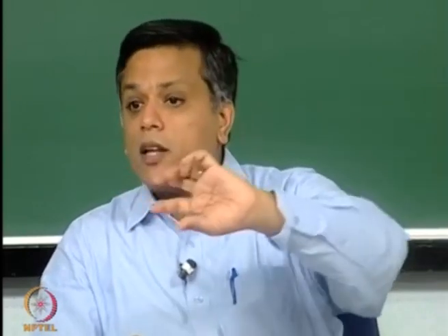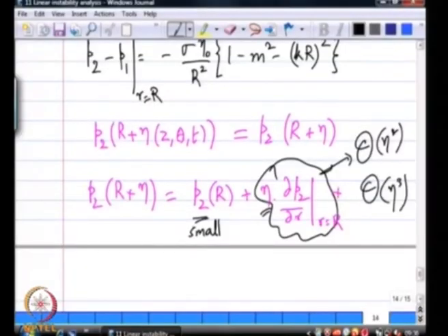If the cylindrical jet had a mean swirl velocity, okay, which we are not considering, as we are considering two cases where the fluids are simply co-flowing, then this order epsilon correction would require the second part, where the perturbation pressure would have terms coming from here which are order epsilon.